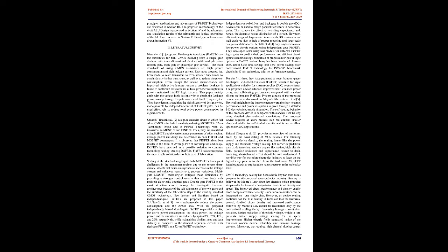Leakage is found to contribute a larger amount of total power consumption in power-optimized FinFET logic circuits. This paper mainly deals with the various logic design styles to obtain leakage power savings through the judicious use of FinFET logic styles. They have demonstrated that the rich diversity of design styles, made possible by independent control of FinFET gates, can be used effectively to reduce total active power consumption in digital circuits.